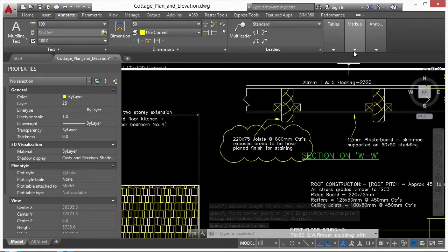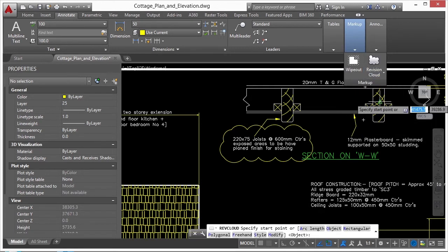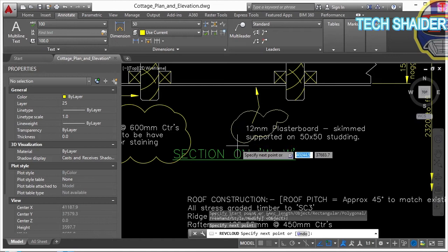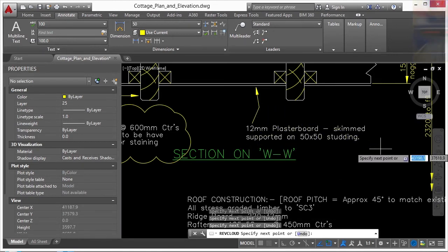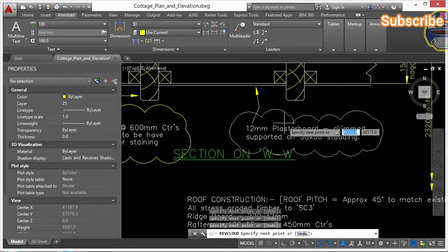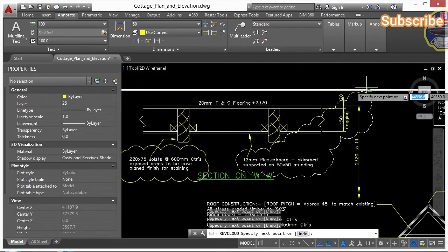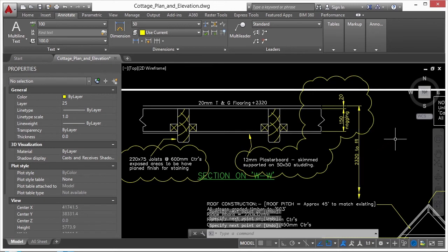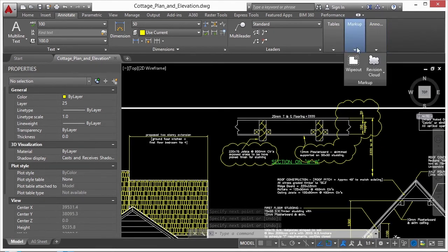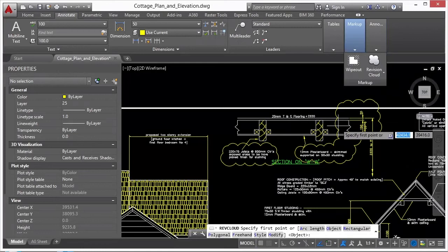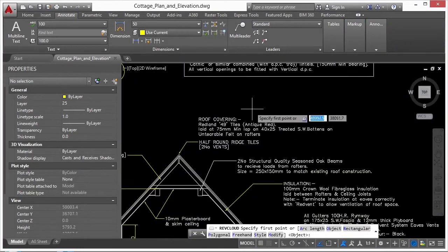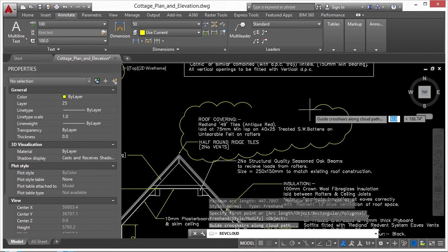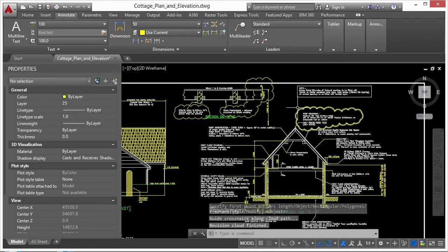It's that simple. Now, if I pick the polygonal option, that gives me a little bit more freedom, and I just move where I want my revision cloud to go, and I click. And I can keep making great shapes. So if I've revised all of this, I can do that, and there's my revision cloud. Now, if I go to the freehand option, let's say I go to this note here, it just comes like this. That one's very easy to use as well.